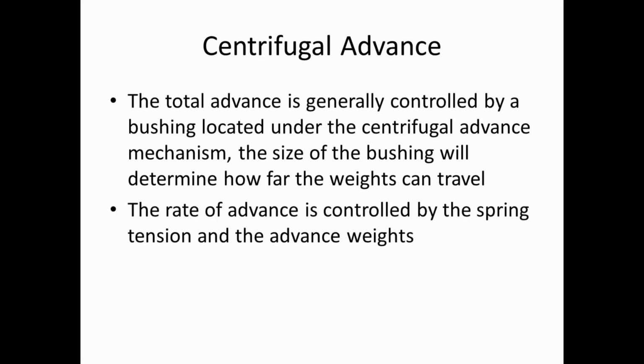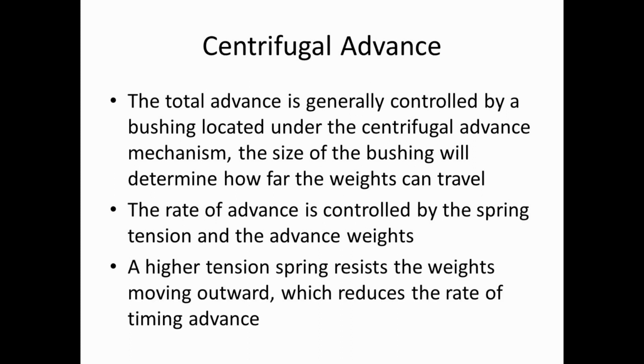The rate of advance, so how fast the total timing can be achieved, is controlled by the spring tension and the advance weights. If you have a high tension spring, it resists the weights moving outward. So that reduces your rate of timing advance.